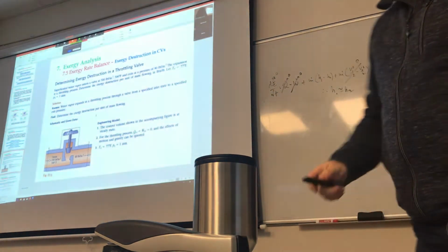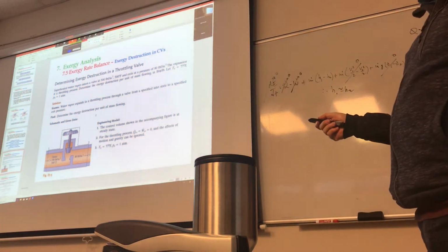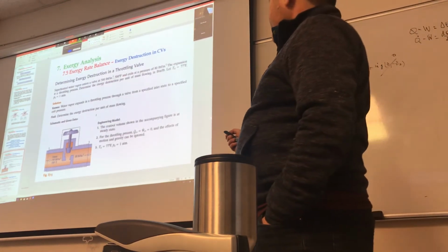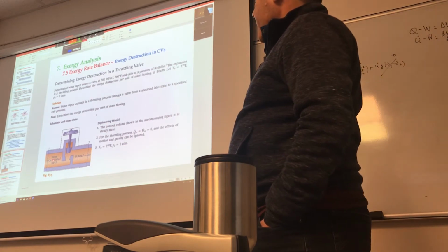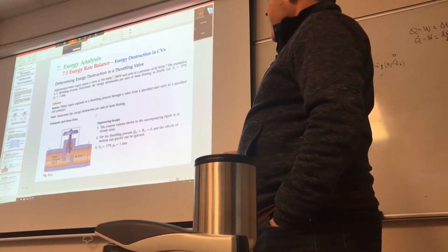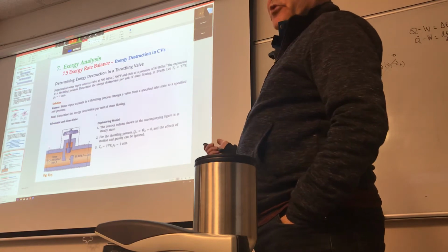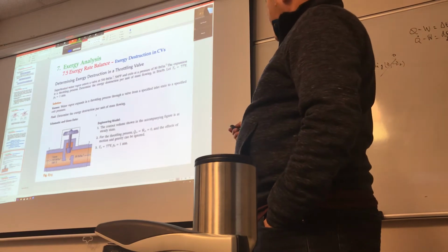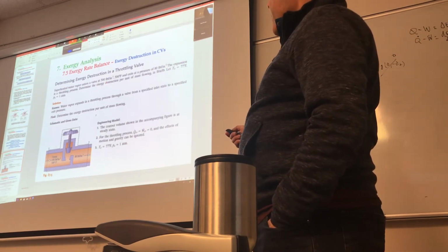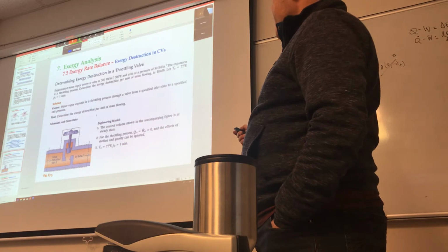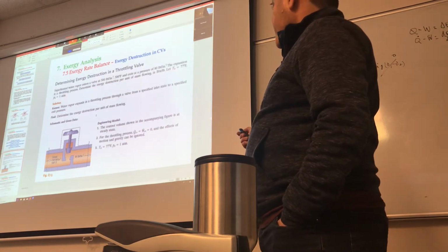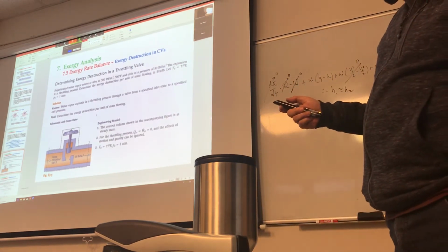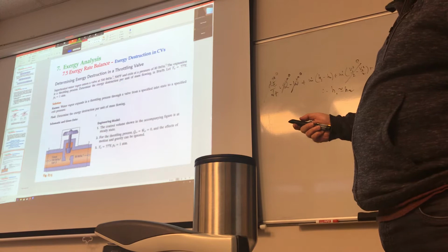So it says superheated vapor enters the valve at 500 pounds per square inch, right here, and exits at a pressure of 80. So you're coming in at 500, you exit at 80. Remember, the goal of this is really a pressure reduction. We would be using this in refrigeration cycles a lot. And it's asking you to determine the exergy destruction per unit mass of flowing, and obviously the dead state is given at 77 and 1 atmosphere. So how do we deal with this particular problem?